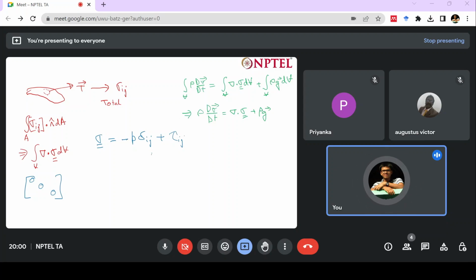Secondly, this lets us decompose our stresses like this. So P here, we are assuming our thermodynamic pressure is acting similarly in all three directions. So this is basically an average pressure, and that is itself acting in all three directions. That gives us a nice way of working around the dynamic equations that we are currently doing. So this is our thermodynamic pressure, not the mechanical pressure.